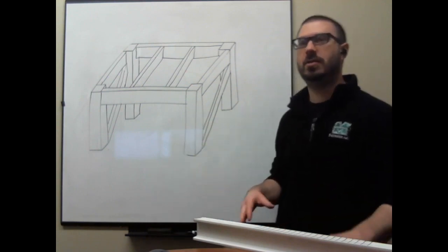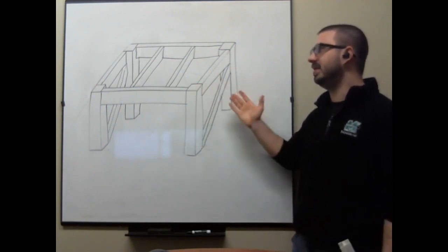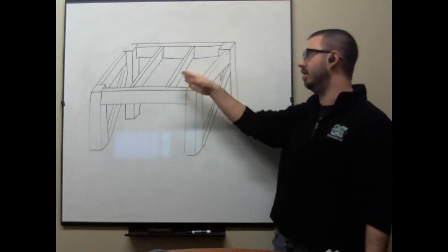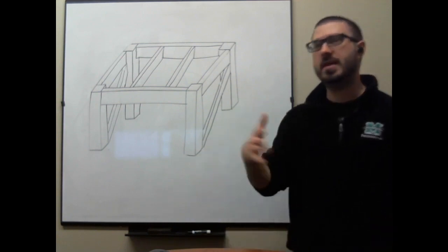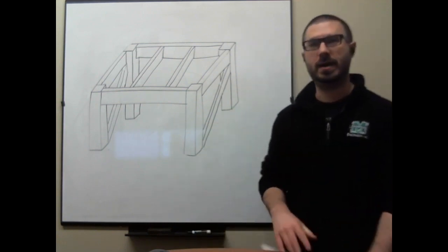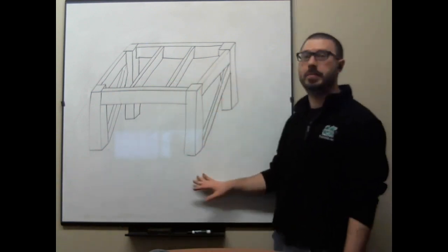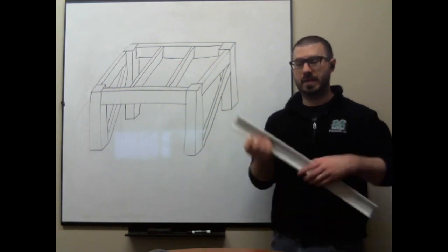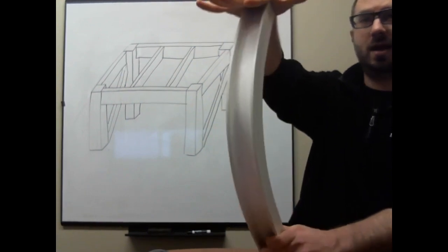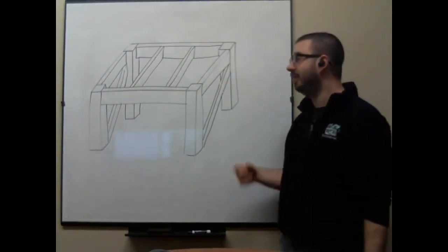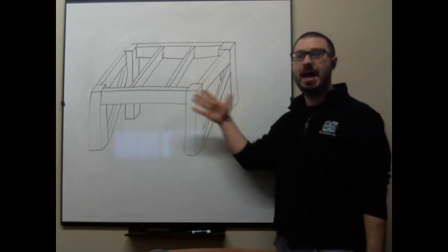But what I have here is sort of a conceptual view of a framing plan of a building. And it's a really simple framing plan. There's just 4 columns and a few beams and whatnot. But this framing plan really does demonstrate everything that you would find in a building like this, okay? And there are really four main elements that go into a framing plan like this. There are the beams, the elements that are designed to be bent. There are the columns that are pushed down and want to act like this. There are the connections, either bolted or welded, but the connections that connect elements together.